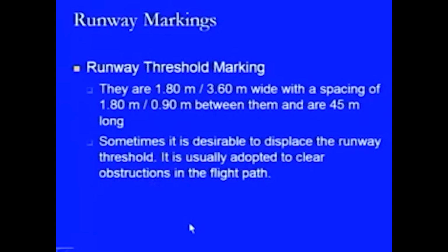Sometimes it is desirable to displace the runway threshold, and it is usually adopted to clear obstructions in the flight path. If there are certain obstructions on the flight path, then by just displacing the threshold, meaning taking the aircraft to a certain further distance towards the airport, we may clear those obstructions, and therefore it becomes a safer movement.